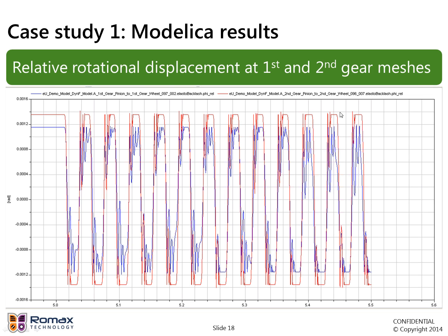The upper limit here represents the gear in contact on the driving flank. You can see it starts off there before we start the vibrations. That's the driving flank where it's been turned, and then as we initiate the vibration, suddenly it loses contact on this side of the gear, this side of the backlash, and flies across the backlash region and impacts on the other side. And you can see this sort of bouncing behavior as the tooth impacts. And then as the excitation switches back in the other direction, we get the gear flying back the other way. So we're seeing this rattle behavior, and we're seeing how it bounces when those impacts occur.